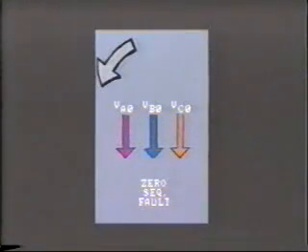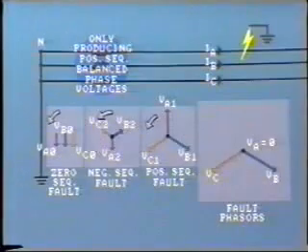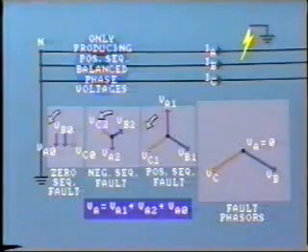In fact, these voltage components have no sequence at all. So they are called zero-sequence components. To review, to get each phase voltage at the fault, we add the three components together. For example, VA equals VA1 plus VA2 plus VA0.